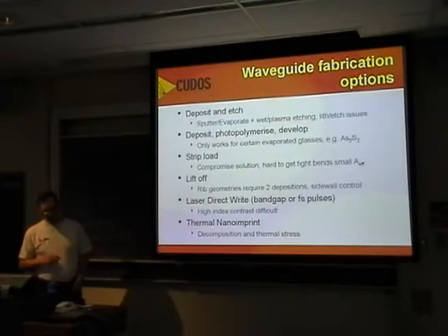a moment. There's also another route one can use where you deposit a thin film, hit it with a high-power femtosecond laser, and photopolymerize the material, and then develop away what hasn't been polymerized. This has been exploited particularly in arsenic trisulfide and a number of other glasses as well, but it is quite specific to the particular glass that you're working with. It does not work with all materials.